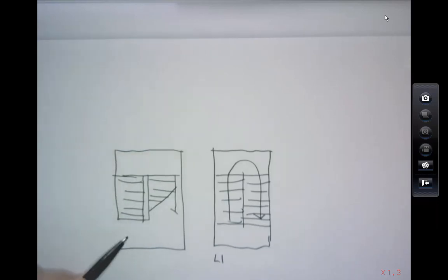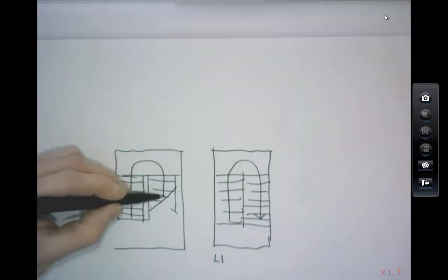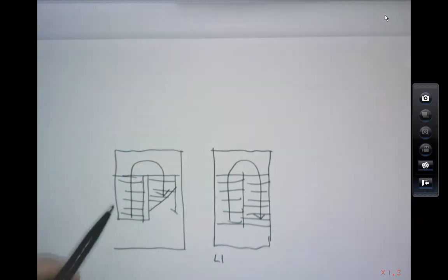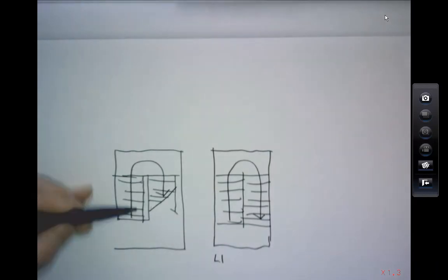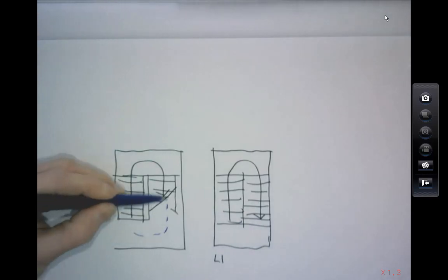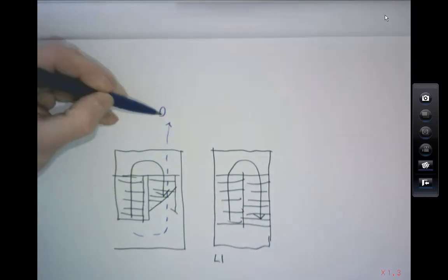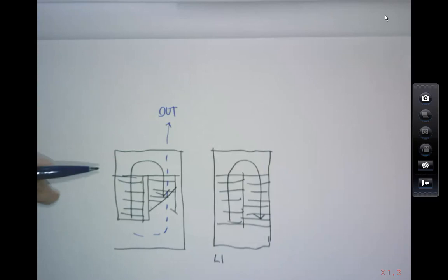So you get to ground. The stairs going up like that. Typically, on an accessible stair, you can't get underneath that. It's too low to go under that half landing. So if you were imagining that you would get to the ground floor and just go back outside like that, often you can't, because you'd be banging your head on that stair.